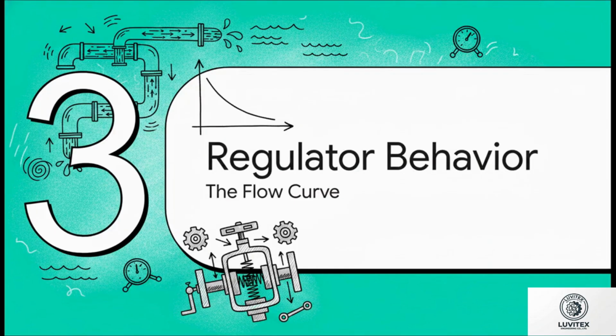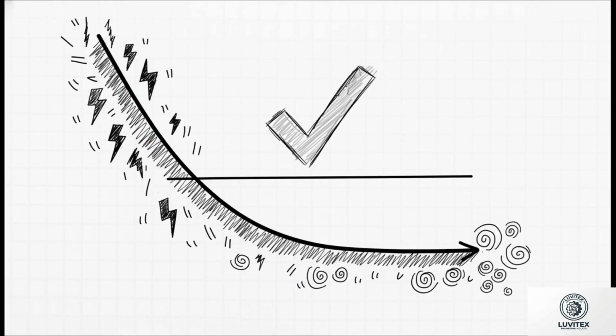Okay, Section 3. Decoding complex regulator behavior using the flow curve. Once we know what we need, we have to understand how these blind mechanical devices are actually going to behave in the real world. Keep in mind, regulators don't have electronic inputs telling them what to do. They are entirely mechanical and respond naturally to field conditions. The hard truth we all have to accept is that no regulator produces a perfectly flat horizontal flow curve. Sure, we all want to operate right in that nice, flat middle section, the ideal operating range where pressure stays consistent even when flow changes.